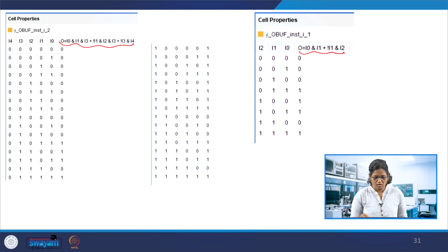With this we have seen a few cases of combinational logic synthesis, that is, the structural primitives and assign statements, and case and if statements. All case statements should have default cases, and if statements should have the else condition, otherwise it would infer a latch. Whether a priority structure or a mux structure is realized depends on whether you explicitly specify all the conditions. If yes, it will go for the realization of muxes. If not, it will be a priority structure.